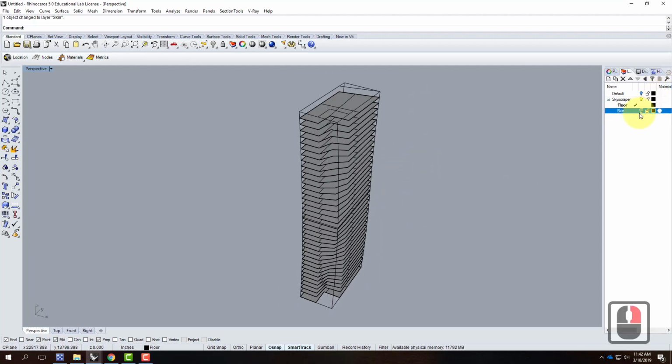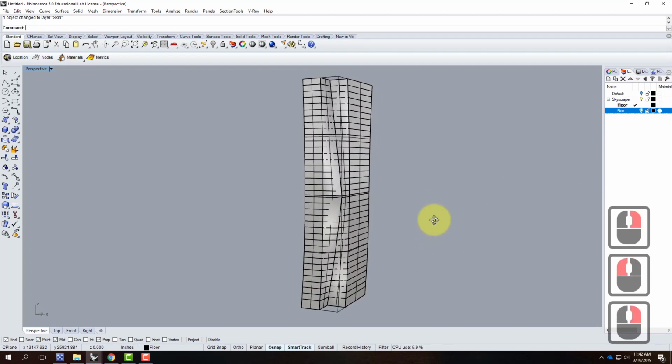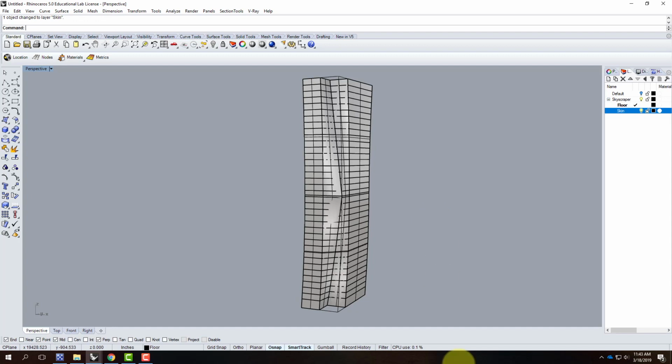That's good. But I also need to have all the ceilings for those floors, because there's always space between the floor and the ceiling below. It's usually called the drop ceiling. For example, in this room, we're seeing the very bottom chord of a truss there. That brown piece of wood that goes across is not supporting the whole roof. That would not be enough to span that distance and support the roof. So up above this level is actually a whole truss system. It's about 4 feet of trusses and ducts and lights and whatever else that's up in there before the roof is on top. Same thing happens in a skyscraper. You need space in between the floors. So we're going to call that 4 feet.